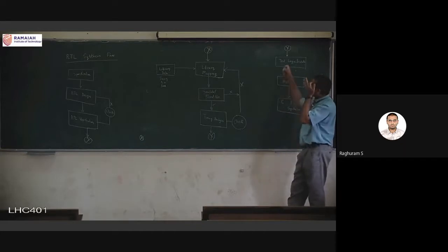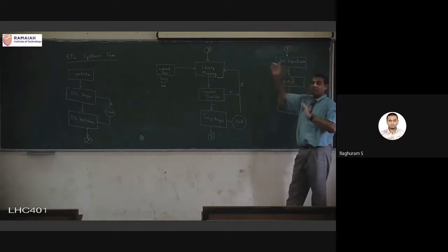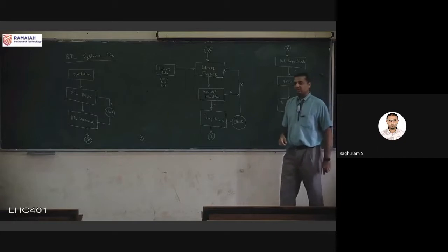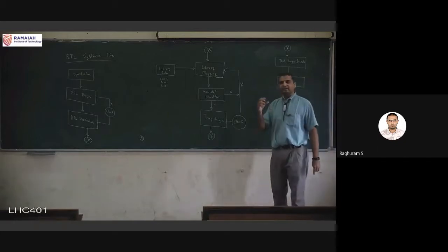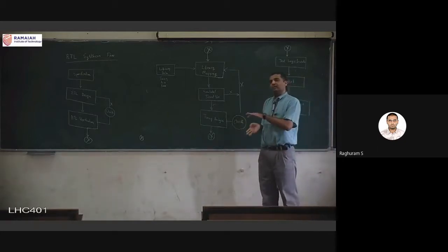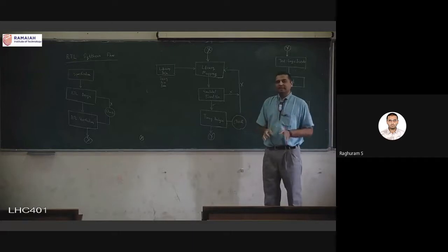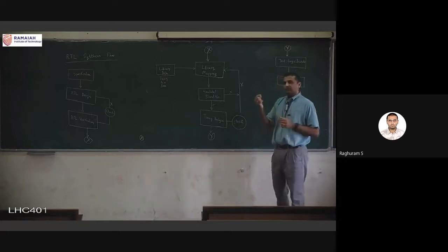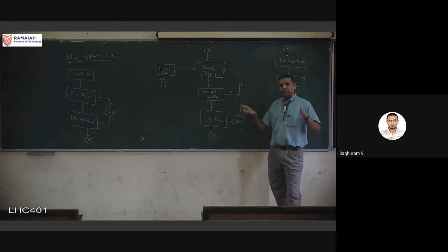And now this comes into the picture. It's not gone to the end user. It's still with me, the designer. And what is the meaning of this test logic is every gate in the design can operate in normal mode or in test mode, and there will be a pin as part of the inputs to decide whether the gate is operating in normal mode or test mode.